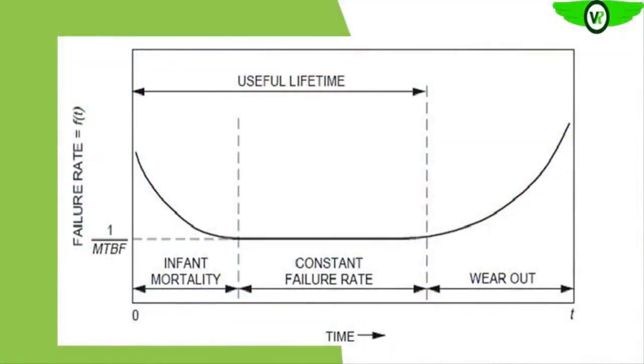design error, or manufacturing error at the manufacturing plant, and even bringing the equipment from your manufacturer to site. Transporting, that is not properly handling the equipment during transportation. All of this can induce some fault condition that will result in infant mortality or early failure of the equipment.